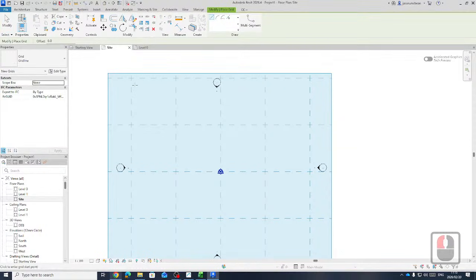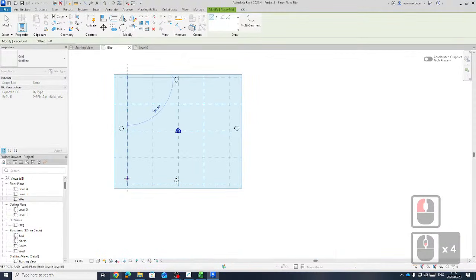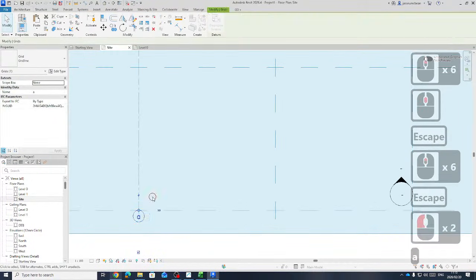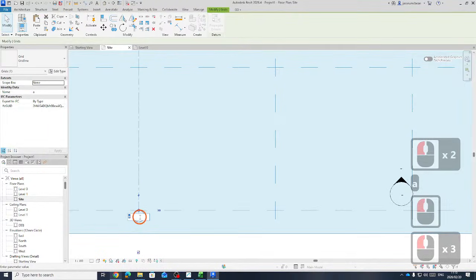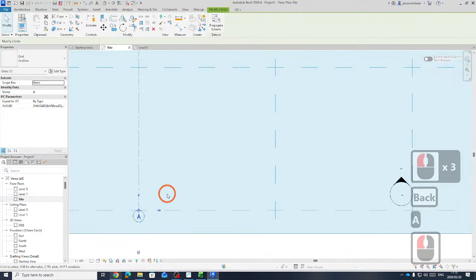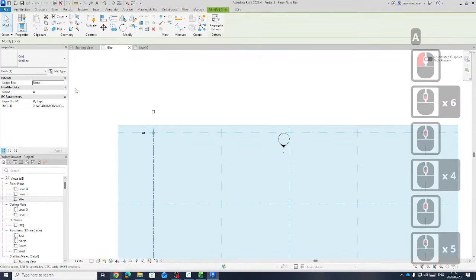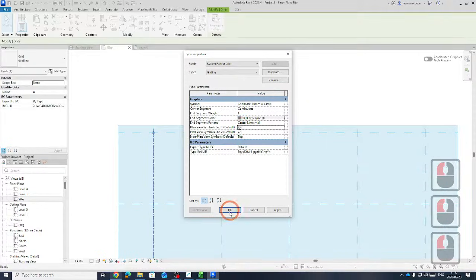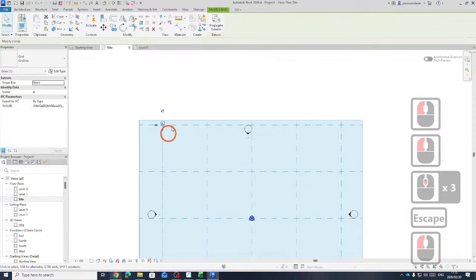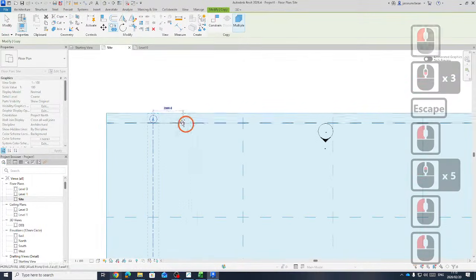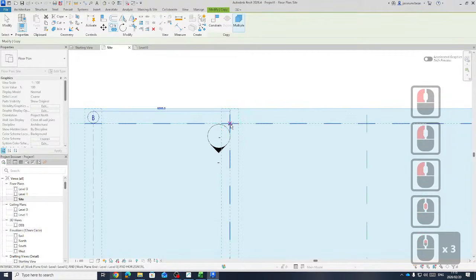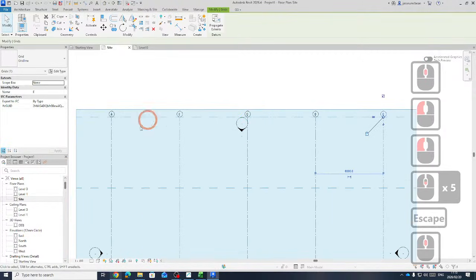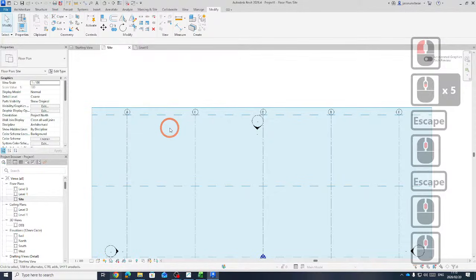This is slightly different because as you start drawing the grid, it will always start with a number, but if I change that to A, let me just change it quickly to A. So whatever system you used last, it will continue with that system. Families, I just want to switch on both grid heads for now. Just follow what I'm doing, you'll get the hang of this. Now, if I duplicate this, this is different. It will start adding. So it's a slightly different workflow. ArchiCAD will just duplicate the same one. Revit can never have duplicate grids for a very specific reason.